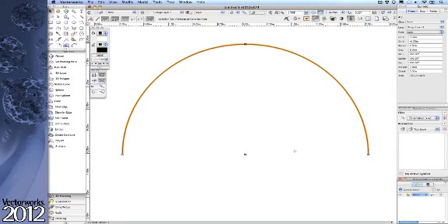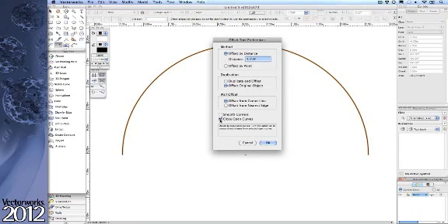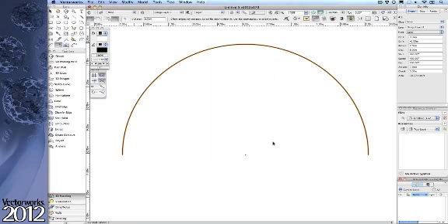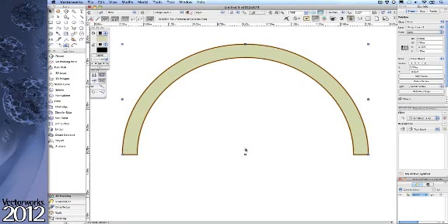Here's yet another time saver we're all going to appreciate. For example, we'll use this arc and then choose the Offset tool, and simply by entering the Offset dialog, we'll check that box that says Close Open Curves. You can also set the offset distance, and you're ready.